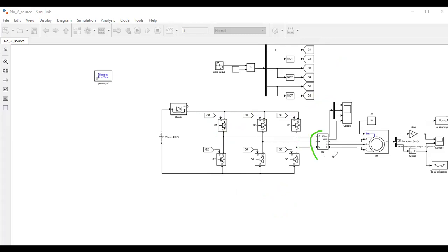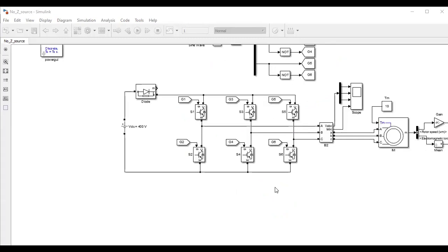After that, this is a voltage measurement block, with A, B, C. We can measure voltage and current; if you see here, there is a voltage and current option. If you zoom out, you will clearly see this is the three-phase voltage VABC and three-phase current we can measure here. This is a Mux, meaning a single input and many outputs.